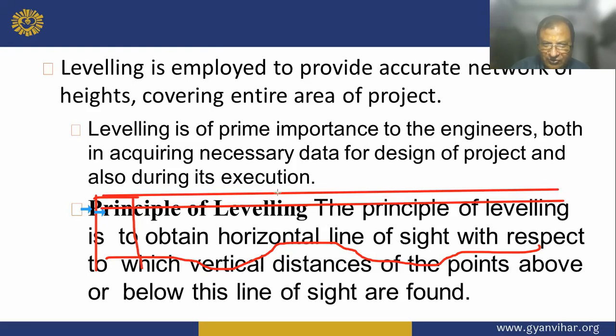So you require to find this height, here this height, here this height. This is, my dear boy, the principle of leveling. The principle of leveling is to obtain a horizontal line of sight with respect to which vertical distances of the points above or below this line of sight are found.